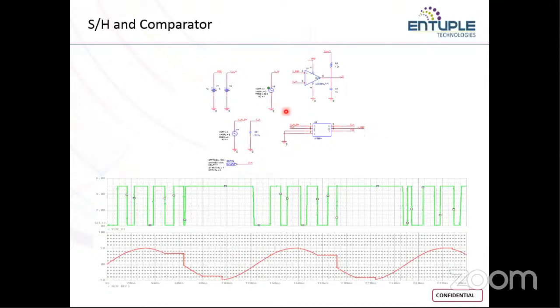Either way, it is going to be analog data. Either you can use a sample and hold IC, which is LF398, or you can directly give an analog input voltage of any value. Mainly, we have to calculate it for three levels of voltages. One is the zero level, another is the mid level voltage, and the other is the full scale voltage level. So either you can go with this approach, or you can make use of a sample and hold IC.